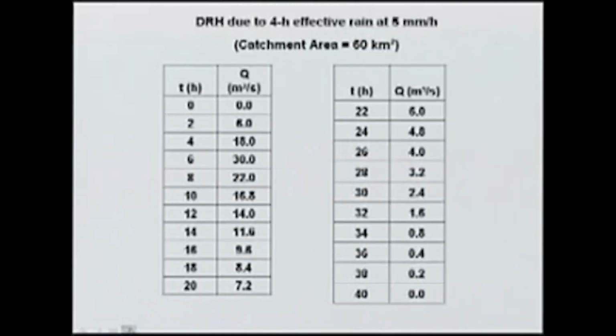So, any duration other than the multiple of the given hydrograph duration, we can obtain the unit hydrograph using the S curve, and this can be used to obtain even for higher durations. For example, if we want 6-hour duration, we can still do the same thing, but suppose we want 6-hour duration, we may again do it by first obtaining the 2-hour unit hydrograph and then using the superposition, superposing it 3 times to get 6-hour unit hydrograph. So, it depends on what we find more convenient, but S curve can be used to derive unit hydrographs for any duration, which is not a multiple of the given duration.